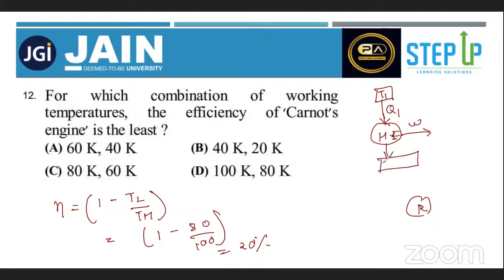So there will be a heat loss, which will be at T2, in terms of Q2. When I refine this, we write it as 1 minus Q2 upon Q1, lower by higher, or I write it as 1 minus T2 by T1. Because here I want to supply the higher temperature. And using this only we can write down the work done also.